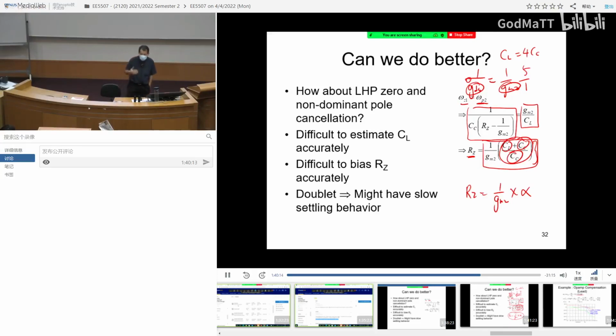Now, if you design a very high resolution ADC, you can probably get down to 0.1% mismatch. Okay? All these require you to use large area devices, because the larger the area, the better the matching. So that is the de facto rule of thumb. So it's possible, but no matter how good it is, there is always a certain percentage of mismatch.